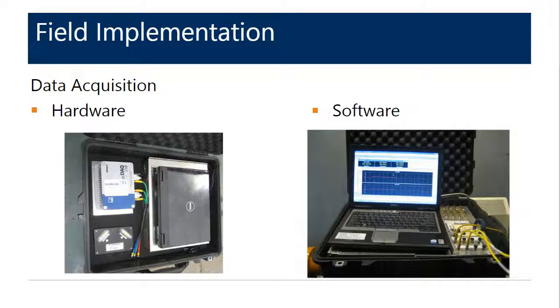The photo on the right is monitoring strain and span position as the testing is being conducted, for immediate indication of the operational loading that the machinery is seeing. We have provided complete standalone data acquisition systems similar to what you see here to bridge owners for their own use to measure span imbalance.